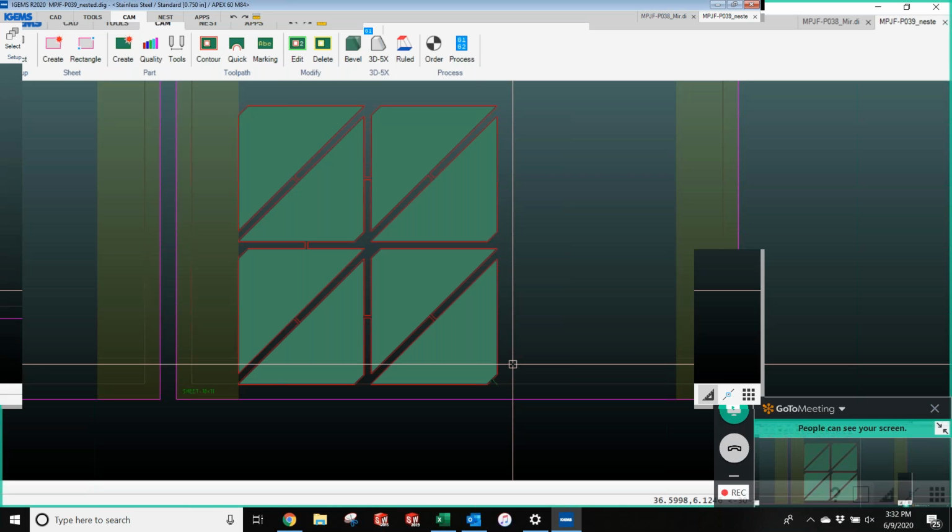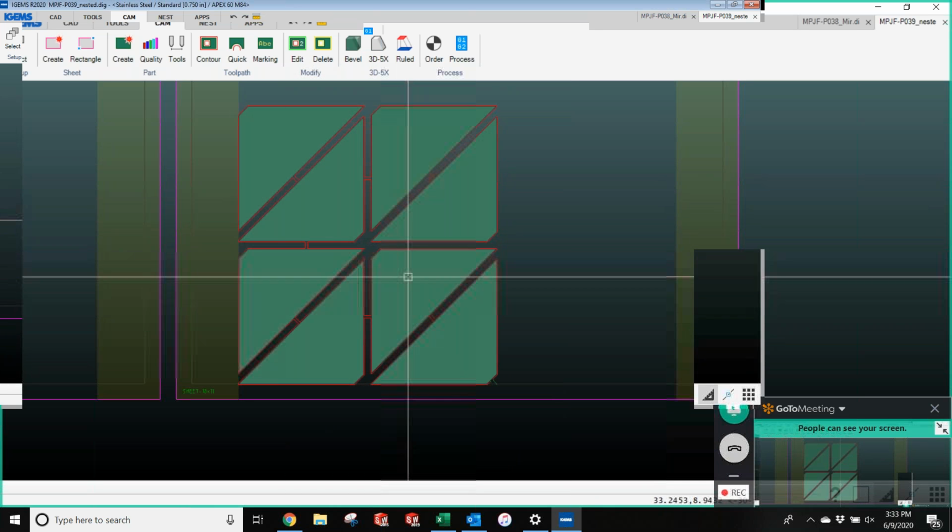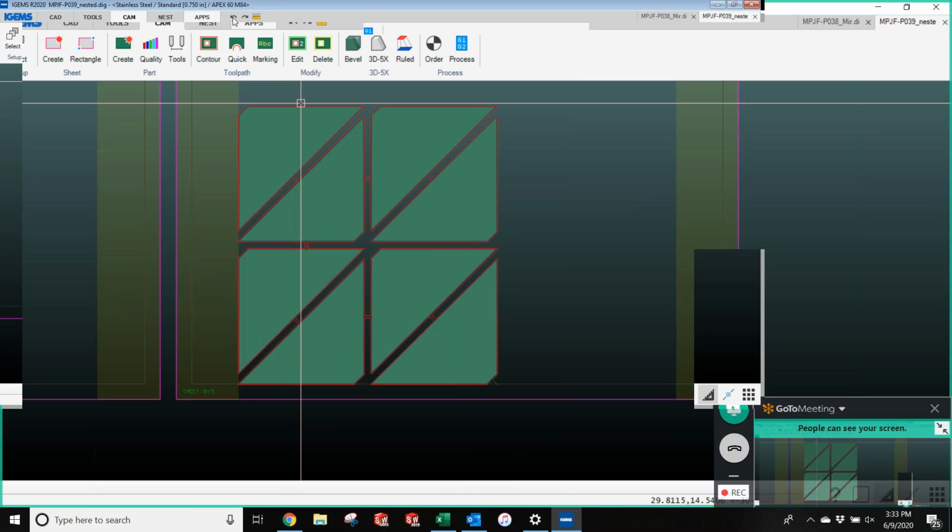So if you can minimize pierces on something like this, then there's less likelihood of things going wrong, because usually once it's cutting, things go well. Like I said, most of the time if you're going to have an abrasive clog, it's going to happen at that initial pierce. Okay. So that can be a bit of a time saver sometimes. So that's how that one works.